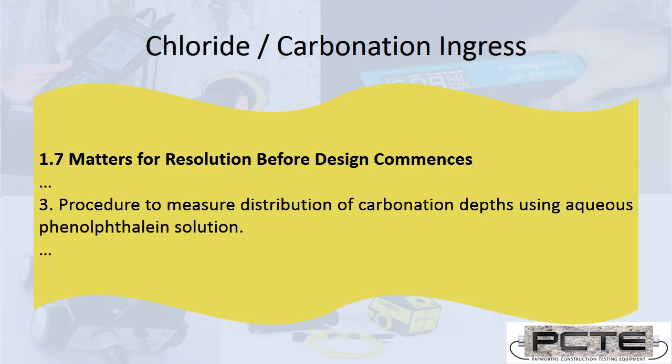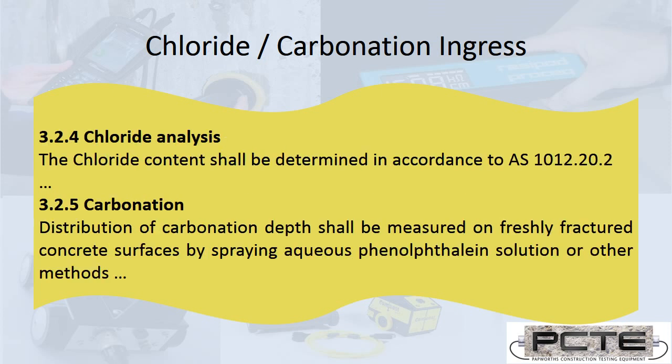So, the section of the standard that discusses chloride and carbonation ingress, I've called out carbonation in particular because it's got a little quirk in that they specify that before design commences, before the consultant starts working with their client on design, they need to come to an agreement on the methods to do their carbonation testing. Additionally, they specify an Australian standard for chloride analysis, and they indicate that carbonation can in fact be used, and in fact shall be used on concrete surfaces to measure the depth of carbonation using the phenolphthalein method.